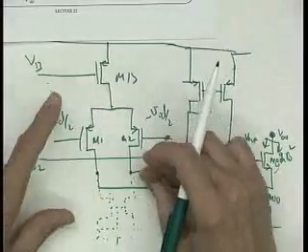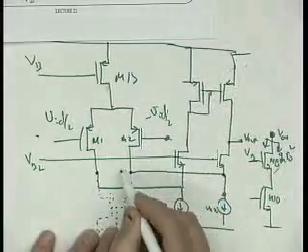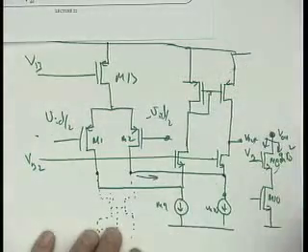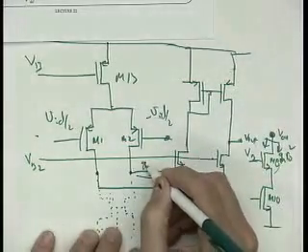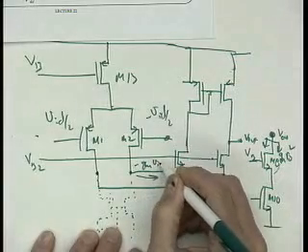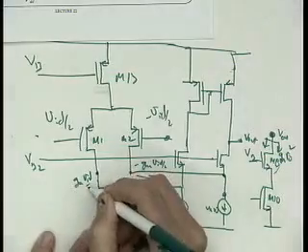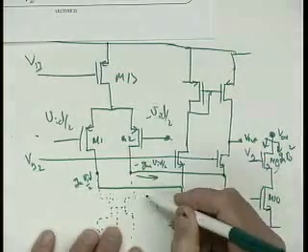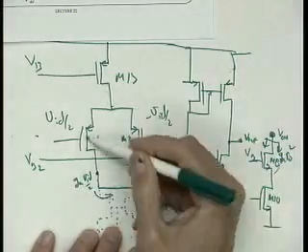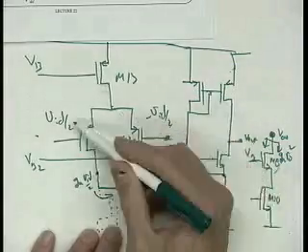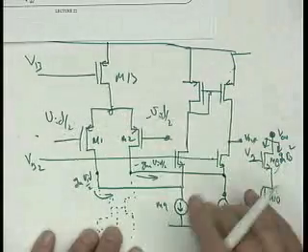So we're putting a differential current here. We're going to get a current out of here of minus gm times Vn differential over 2, and we'll get one here, gm Vn differential over 2 on this side. So that's the current we're going to get coming out of these two transistors because of this differential input voltage we have here.